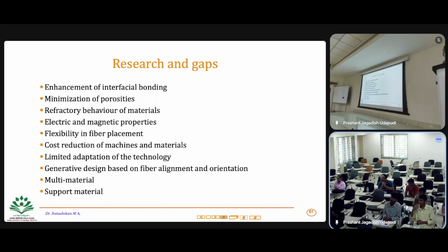And then using the right material, right? And as I said, you don't need to try to decrease too much. Otherwise, if you decrease too much, you will end up spending more time in printing, right? So yeah, there are a few other ways, but I think these are the major parameters that will affect the bonding between the layers. And of course, when you change the material, your bonding may be different, because you have different solidification or curing methods, and that will also affect it.